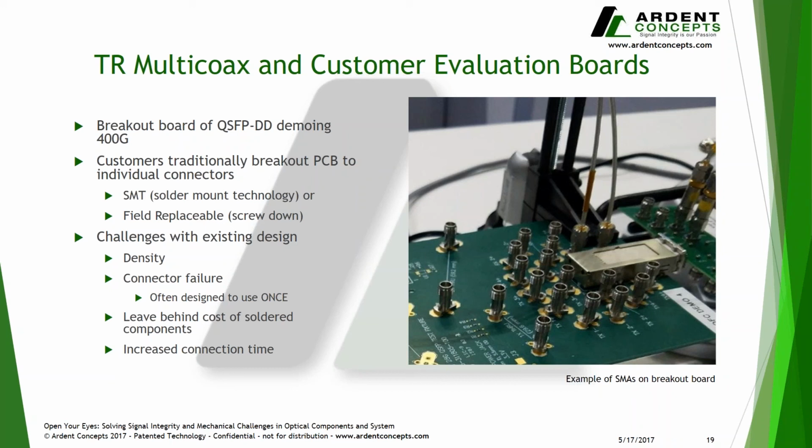Obviously, there are some challenges that we can see here. Density is at a premium, and there's many connections, and they're really tight together. Also, with the solder down type connectors, you are opening yourself again up to failure because you can have poor solder joints, and you may be chasing a solder failure when you're trying to debug a certain line.